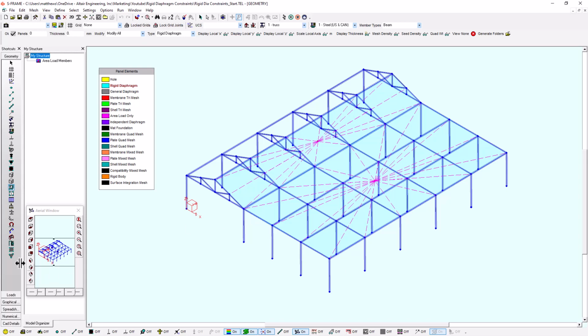If, for example, this flat diaphragm that's in plane with the global coordinate system's XY plane is telling joint number, turn on the display again, joint number 41 to move 2 millimeters in the x-axis. And then the diaphragm on the slope is telling that same joint, which is also constrained in this diaphragm, to move 4 millimeters in the opposite direction. How is it going to know which one to listen to? So we're going to look into what happens when we work with this. We want to avoid situations where these diaphragms are sharing joints.